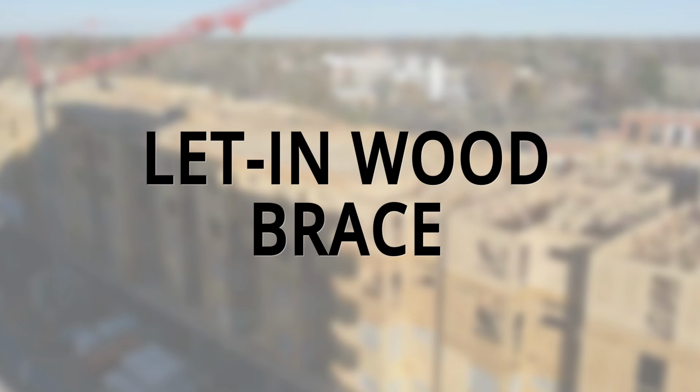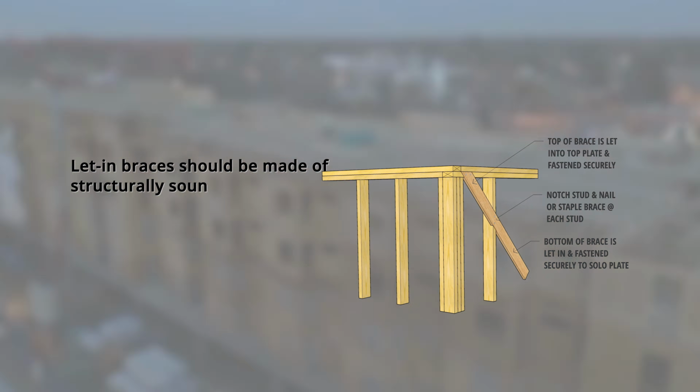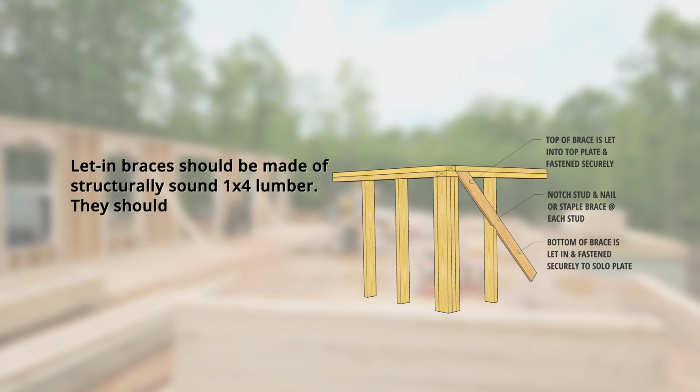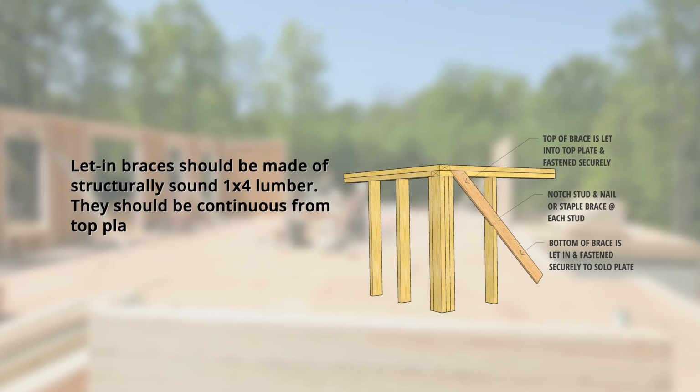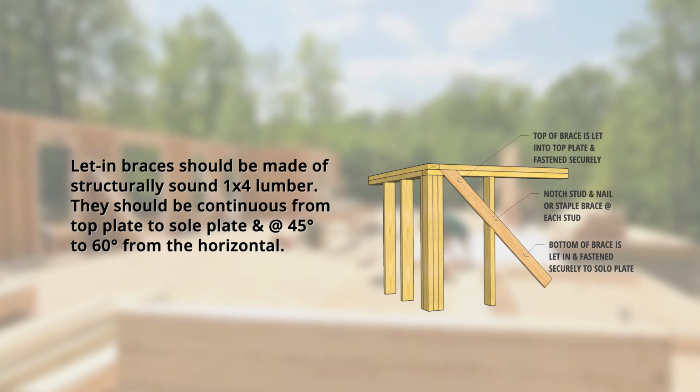Let-in wood brace. Let-in braces should be made of structurally sound 1x4 lumber. They should be continuous from top plate to sole plate and at 45 to 60 degrees from the horizontal. Take a look at this detailed illustration here on the right.